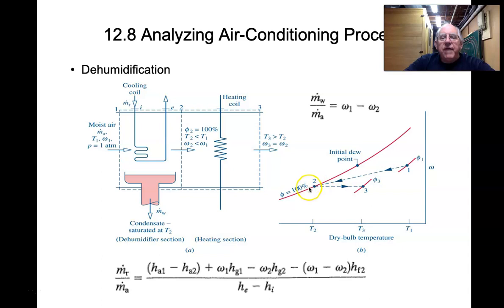The enthalpy value for this term right here, if I were to pick that up, would actually be equal to this value and this value together. And so the psych chart allows you not to have to look at the two components separately, but the two components together as a difference in the mixture enthalpy with respect to the mass of dry air.